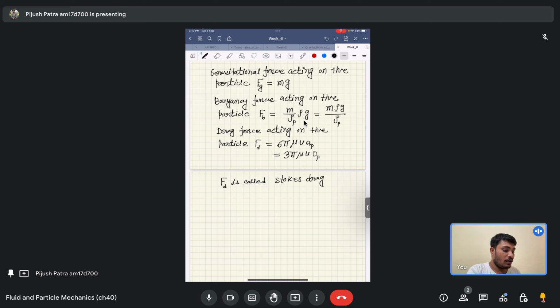One can derive this expression for the drag force from the fundamental low Reynolds number flow problem, where you have to calculate the disturbance velocity field created in the fluid because of the particle's motion, then use the constitutive equations for the stress, and integrate the traction along the surface of the sphere to get the drag force experienced by the particle.